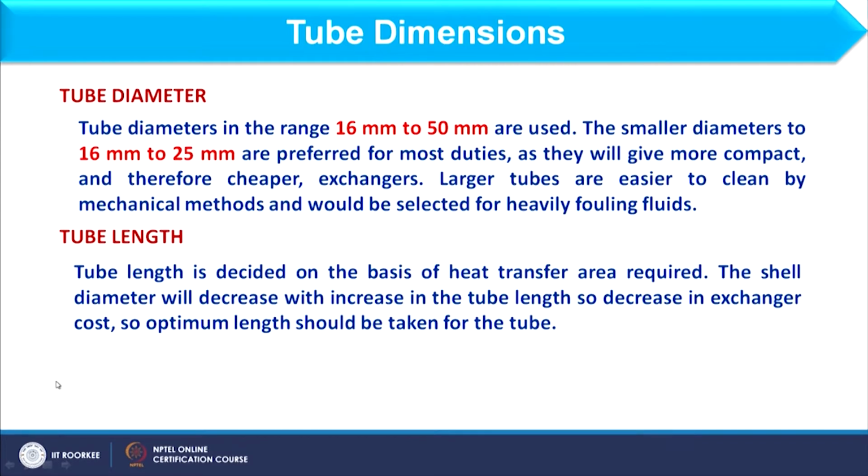However, the complete length can be obtained by adding the tube length, the tube sheet thickness and the cover size also. Accordingly, the complete exchanger length can be finalized, but as far as heat transfer is concerned, tube length will be equal to the shell length.